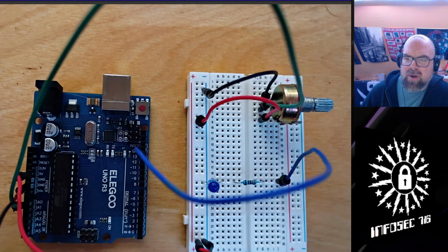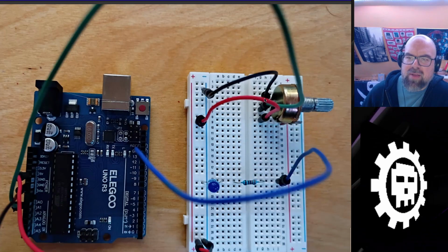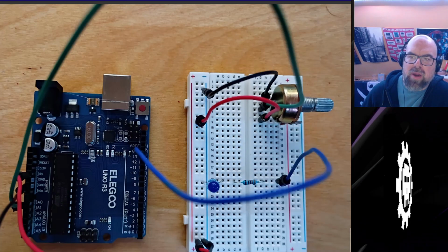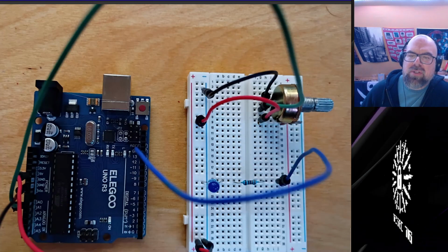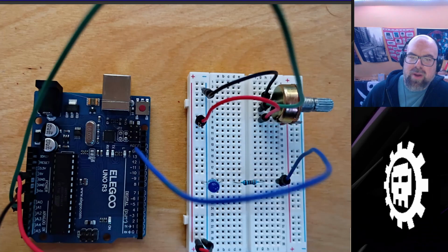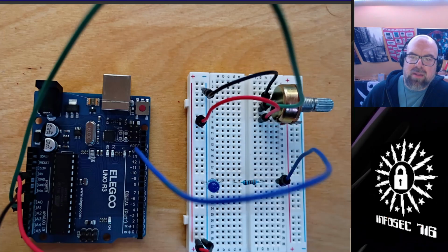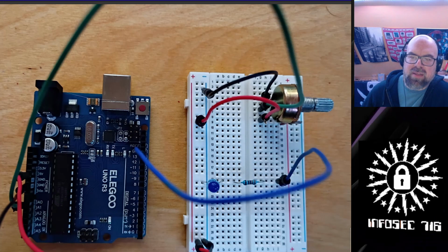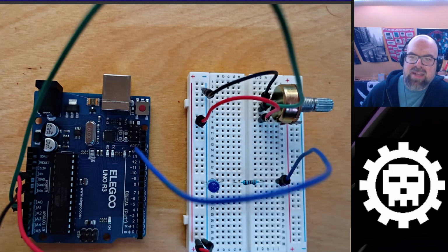They're 2 rows apart. And you see here I've got 3 of these jumper wires, these DuPont wires, connected to those 3 rows of tie points. This red wire is going from our power rail over to this lower pin on the row 8 side.